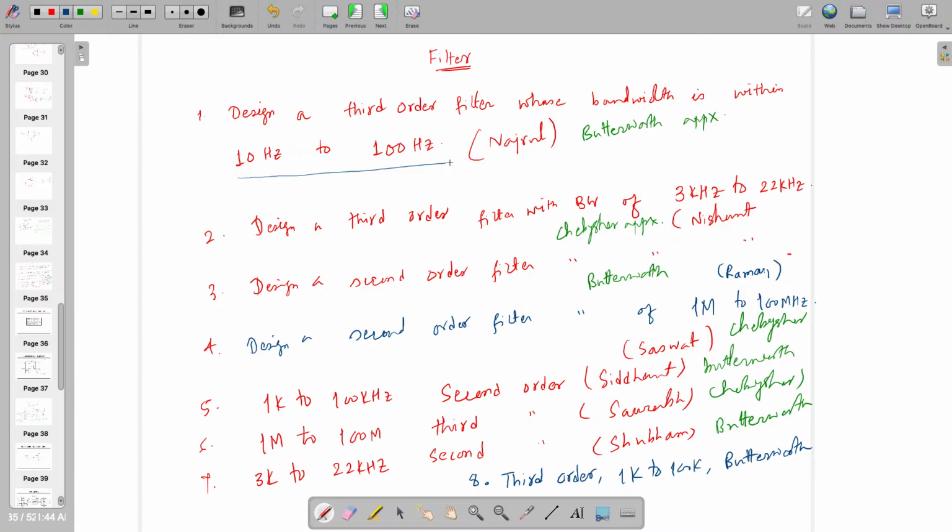So for designing such thing, there are many ways to design. This is how you will go through this Butterworth and Chebyshev. At least what are the approximation, right? If you want to see those approximation, those are given in like the first book of Behzad Razavi, Microelectronics Fundamentals. So it is also given there. Then just you have to replace RC with switch cap, or if you are in GMC, you have to use that entire transfer function, and you have to make the block diagram, right? Through block diagram you can make GMC.